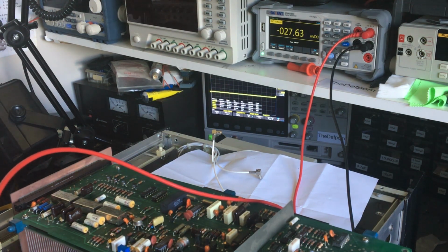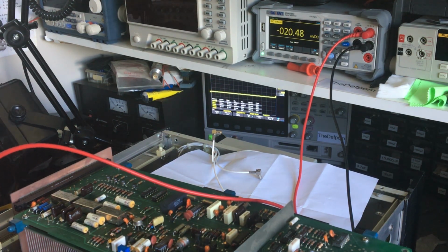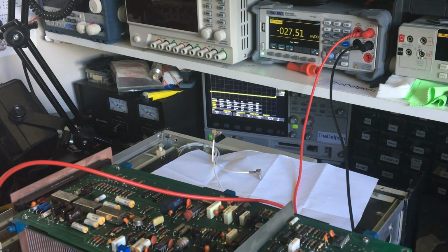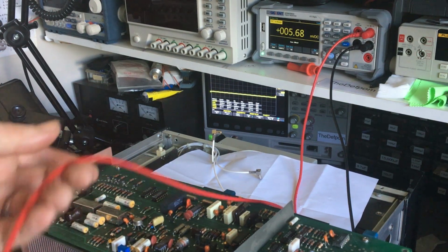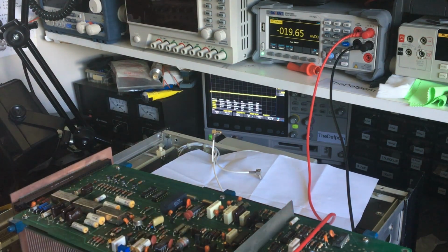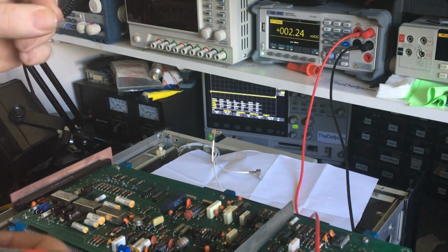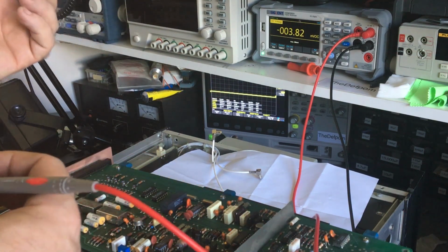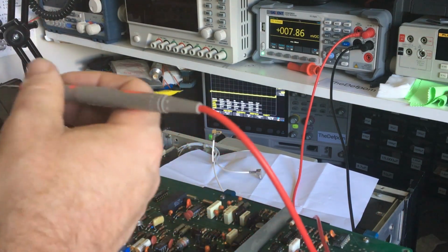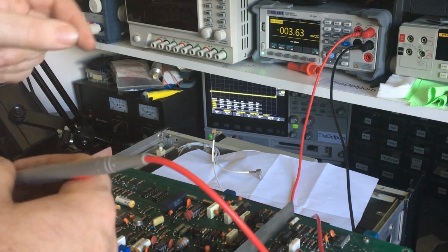Pin 1 and 2 are joined together. It's acting as an inverter in that stage, so this is an AND gate configuration. Pin 1 and 2 are joined together, it's just acting as an inverter. So that first stage is working and that input is correct.